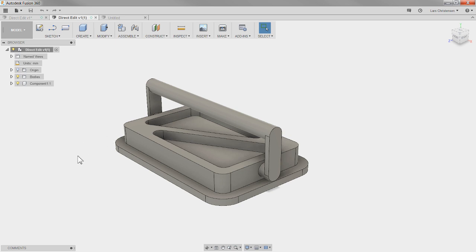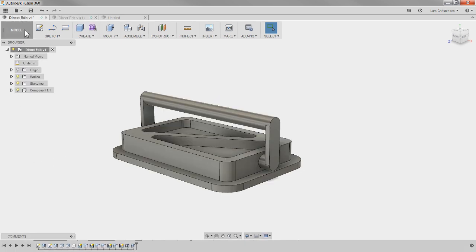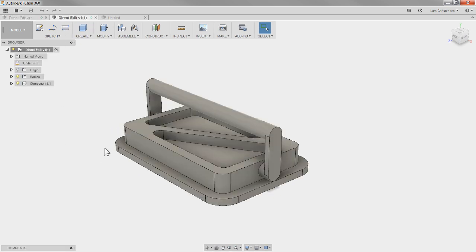And like I said, we can talk more about this if you're interested in learning more about the differences between IGES, STEP and all this. But literally what I did was I took this model, the one with the history tree, saved it out of Fusion as a neutral format called STEP, and then brought it back into Fusion again. And what happens when you save out to neutral formats like STEP and IGES is that you don't get the history tree with it.